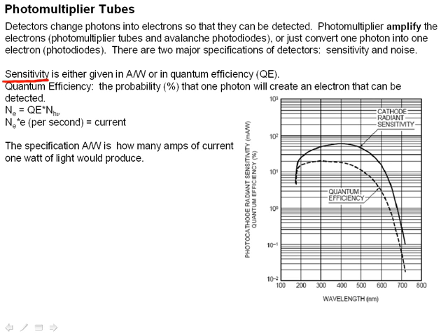So let's look over at our photomultiplier tube. You can see that we have the radiant sensitivity and the quantum efficiency. The quantum efficiency is given by the dashed line and the radiant sensitivity is given by the solid line, and it peaks on the order of 300 nanometers to 400 nanometers. And you'll notice that this efficiency or sensitivity falls off very, very rapidly as we start to get out into the red and infrared region of the spectrum, because those photons don't have enough energy to knock an electron loose, it turns out.